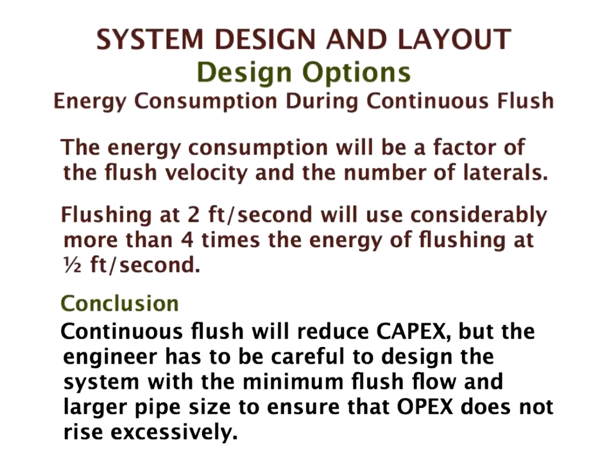So in my opinion, continuous flush will reduce capital investment, but the engineer has to be careful to design the system with the minimum continuous flush flow and larger pipe sizes on the supply lines and the manifolds to ensure that the operating expense does not rise excessively.